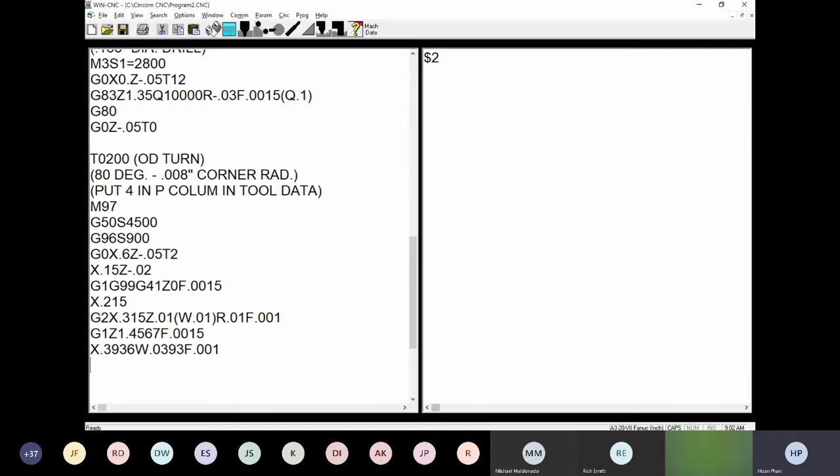And then after that, I can move the Z-axis over a little bit. The distance right here is 100 something, so maybe I can do W 200 with the feed rate turned back on to 1.5.